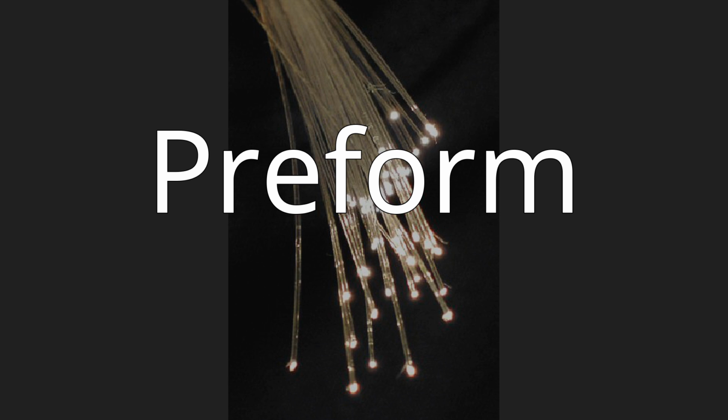In outside vapor deposition, the glass is deposited onto a solid rod, which is removed before further processing. In vapor axial deposition, a short seed rod is used, and a porous preform, whose length is not limited by the size of the source rod, is built up on its end. The porous preform is consolidated into a transparent, solid preform by heating to about 1800 K, 1500 deg C, 2800 deg F. Typical communications fiber uses a circular preform.